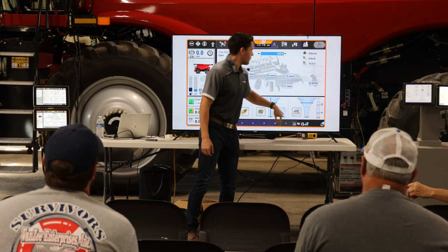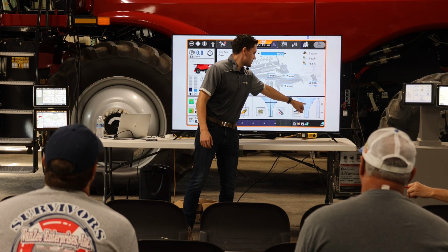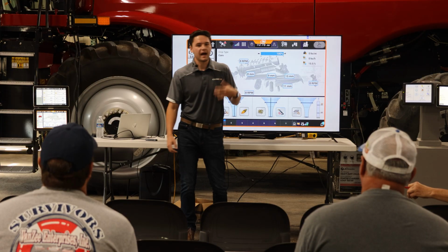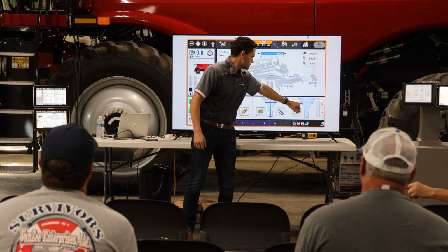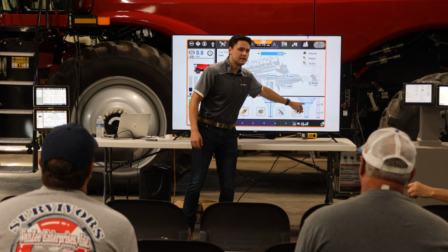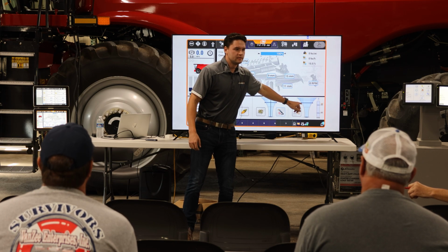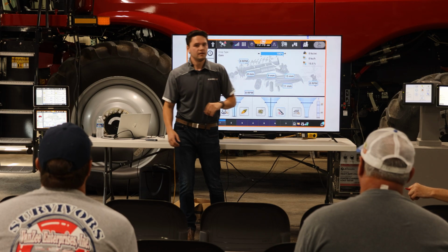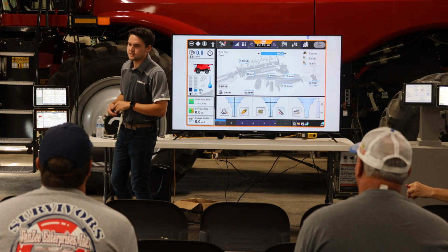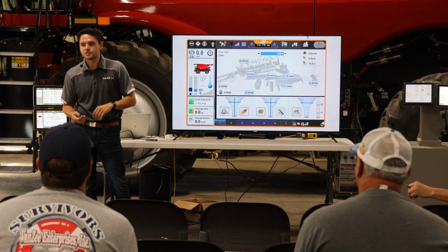So if we want to have our automation making changes more frequently or have a higher response time, we're going to want to keep that funnel fill as close as we can to this point right here. Because that way, if it makes a change, it only immediately will be maybe a minute, 2 minutes, if it's bouncing above and below it, of seeing the issue.